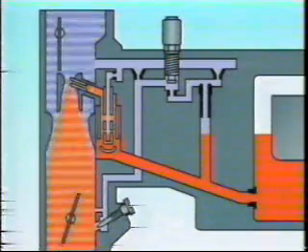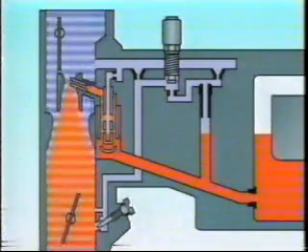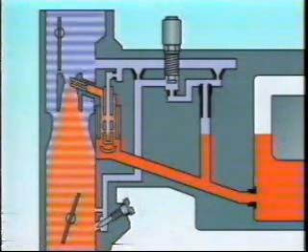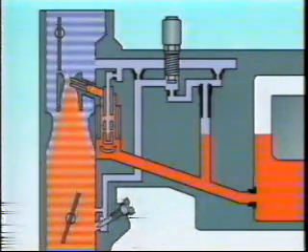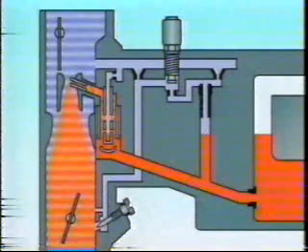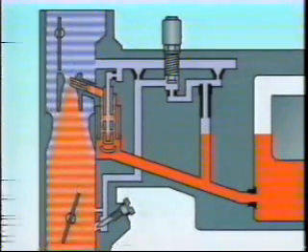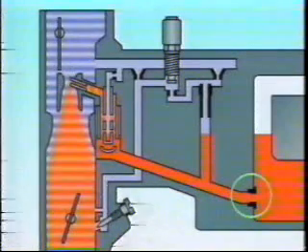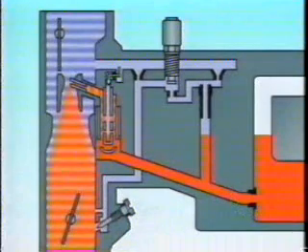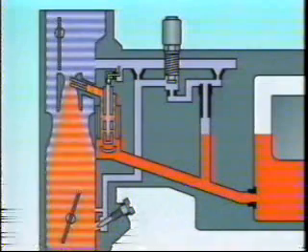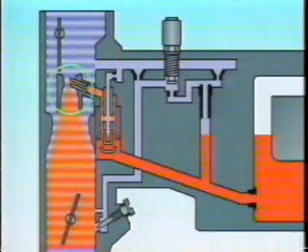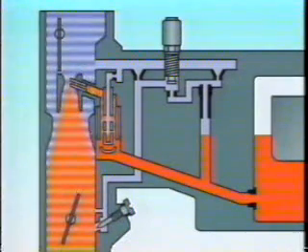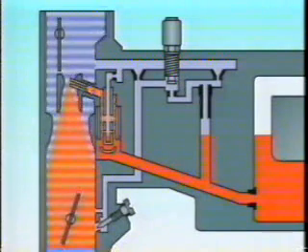The primary high-speed circuit works as follows. When the throttle valve is opened wide, allowing for a higher speed and volume of air to the Venturi, the amount of fuel that is delivered is equivalent to the intake air volume drawn into the barrel. The amount of fuel is controlled at the main jet before it is mixed with the primary air bleeder and injected from the main nozzle. The fuel is atomized by the air flowing at high speed past the Venturi, from which it enters the combustion.